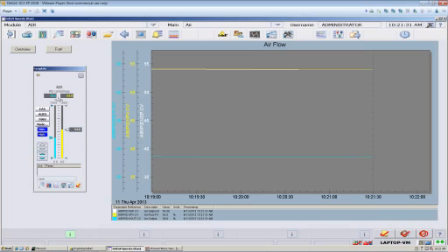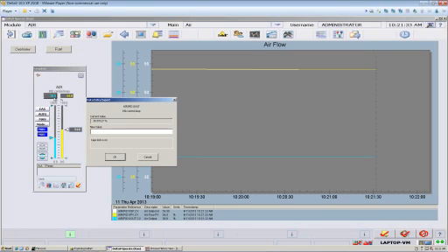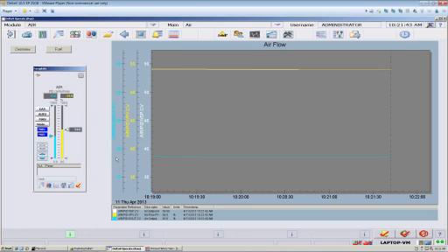So I'm going to make a 3% change. We're at 38.6% valve output right now. Let's step up to 41.6. And there's my change. Now with my charting tool here, the first thing I can do is put my cursor right there and click my mouse, and I can see that at 10:21 and 42 seconds, I changed my valve output by 3%. But my PV didn't change right away.